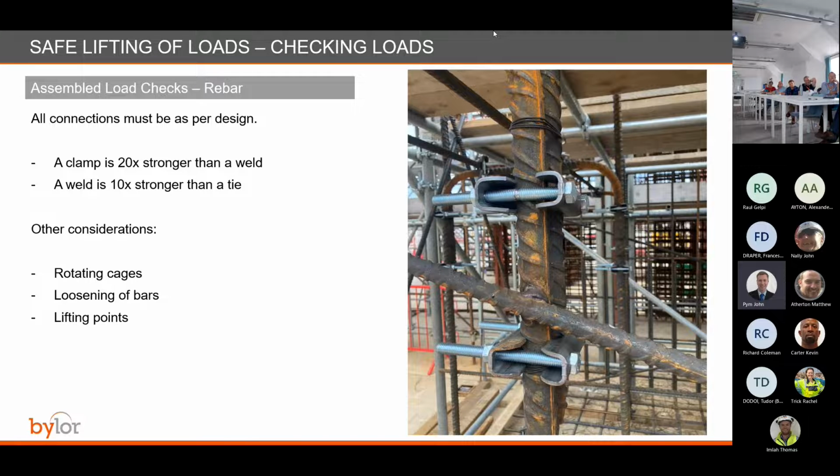Yeah, so we talked about firsts and leading the way at HPC. It might seem obvious, but when you're lifting a cage, you use tie wire. Yeah, that's what everyone else uses. And tie wire is not that great as a structural element when you want to lift something. So the team did a lot of work. Welds, the next thing, you will see that on quite a few sites. For lifting, designated points, welds, lovely, 10 times stronger.